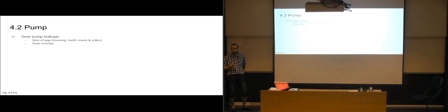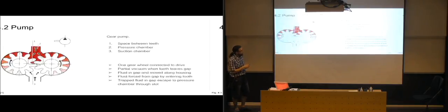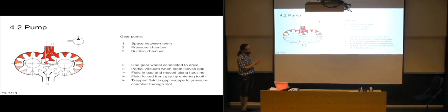Was there a question? If there is a cavitation problem inside. No, you would have risked cavitation problems here if you didn't have this slot that lets the pressure out. So you could have risked a lot of problems in here if you didn't have that slot. But you will have a pressure drop here, and if you're running the pump too hard, at too high an RPM, more than it's designed to handle, then you could risk cavitation there, because you are creating a slight vacuum inside there as the teeth are leaving each other.